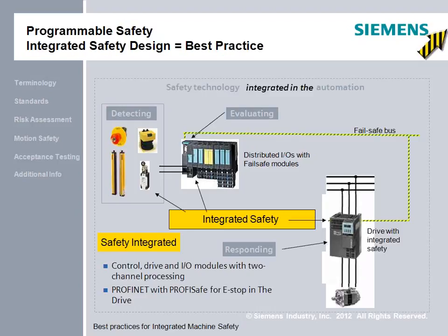You will see this acceptable both domestically in the U.S. and Canada, acceptable in the European Union, the European Machinery Directive, of course, and acceptable internationally. So this is what I would consider best practice. We have the opportunity for the standard control system to bring the drive to a stop under control, along with the safety system to monitor that result.